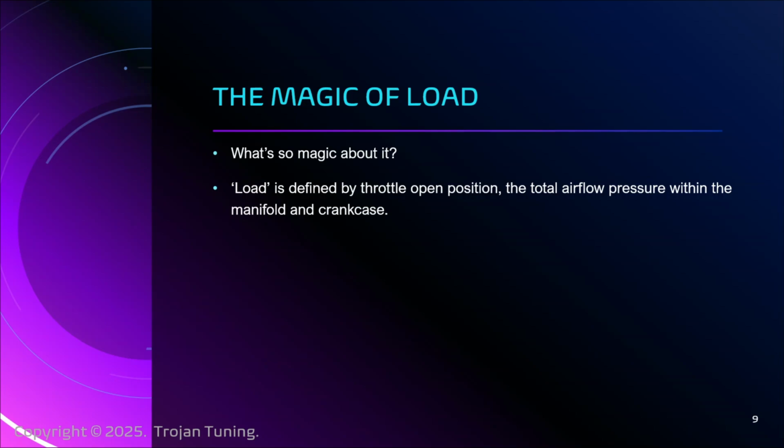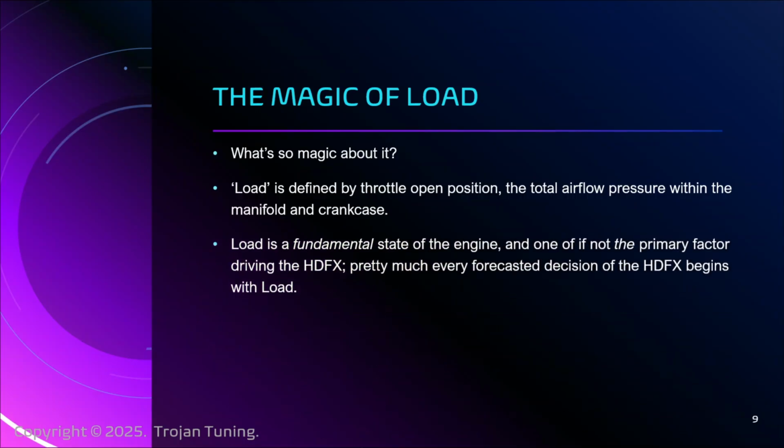Because the whole point of wide open throttle is you open that throttle plate, and the pressure goes up massively inside the crankcase. When that happens, that is a fundamental state of the engine. One of the very first things the HDFX looks at is what is the load right now and where does the load need to go. And it's all about airflow. It is the primary driver of pretty much every decision the HDFX is going to make.